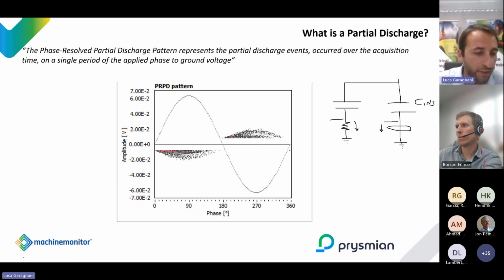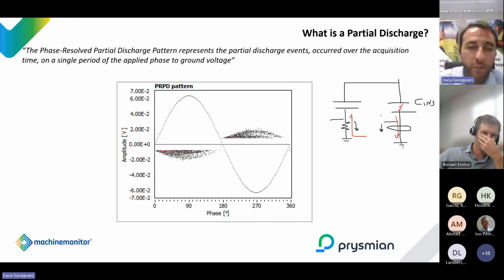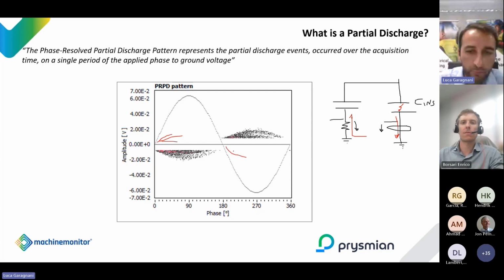And if we correlate the polarity with the physical propagation of the discharge, you know that if you have a discharge in this insulation, this discharge will travel as a current through the ground and back into the high capacitive path, which shows a low impedance path for the current, and go back to the source. So basically your PD is a current generator in high frequency. If you use a CT, the polarity of the high frequency current, the polarity of the PD, and the polarity of the sensor match, and we normally call this direct measurement. So you will see a PD that looks like this in the graph if you synchronize properly.